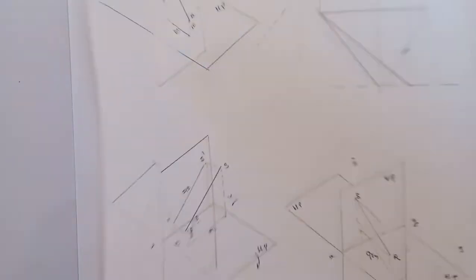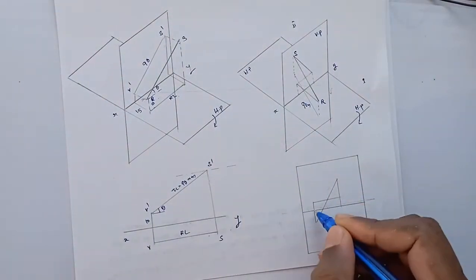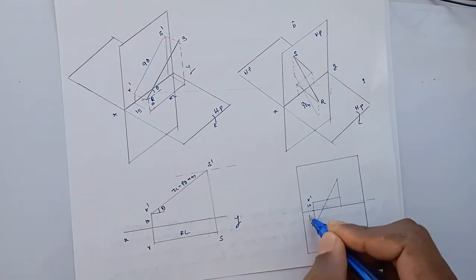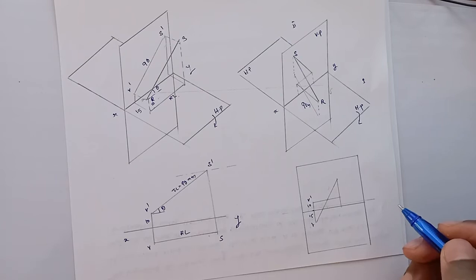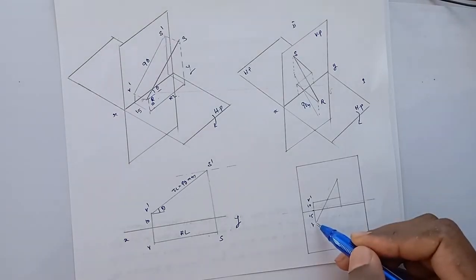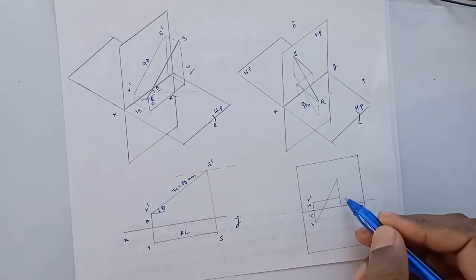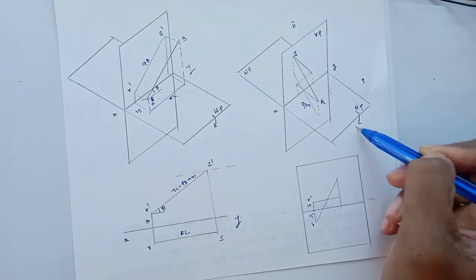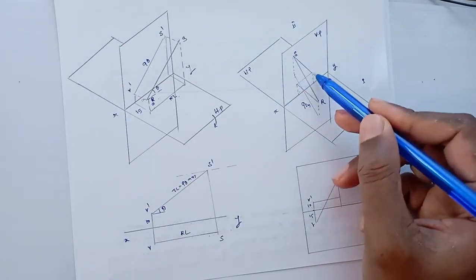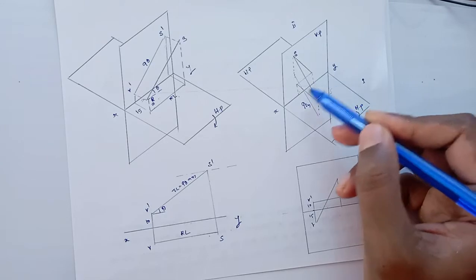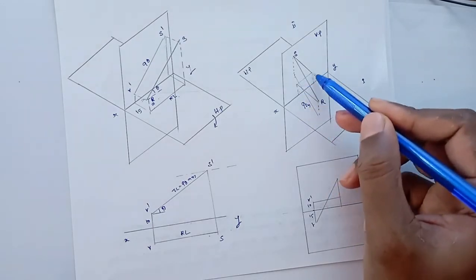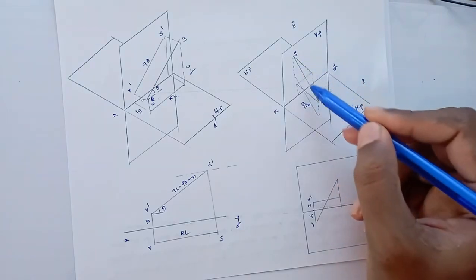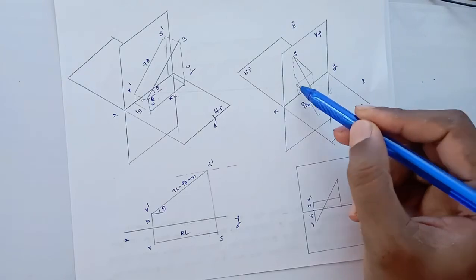So how to draw that projection? First, very simple. You have to first spot the point R. This is R dash and this is R. This is 10 mm above HP and 15 mm in front of VP. That we already know. Okay. And after that, this is your front view. We don't know the length of the front view, right? Looking from this side, we will get the front view like this, parallel to the XY line in between these two projection lines. This is our front view, but we don't know its length. If we can spot the top view, we can find out this length.